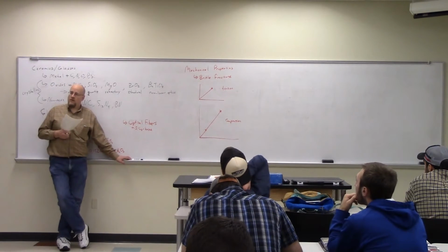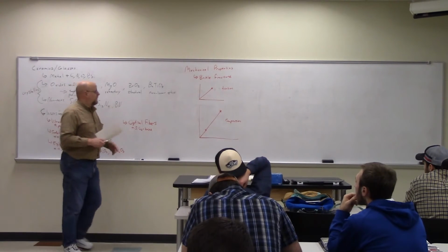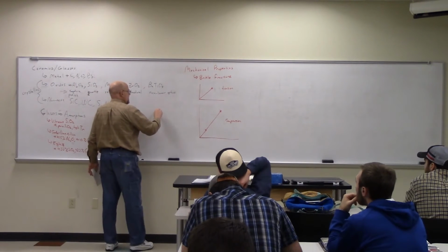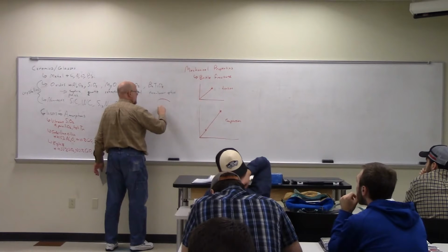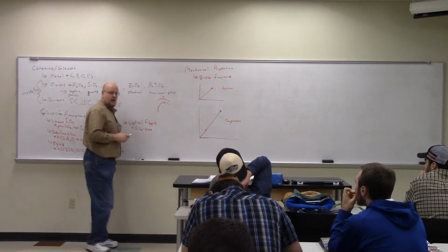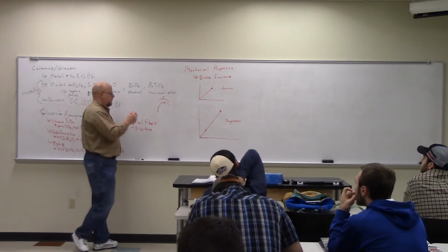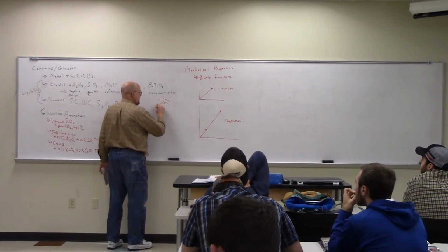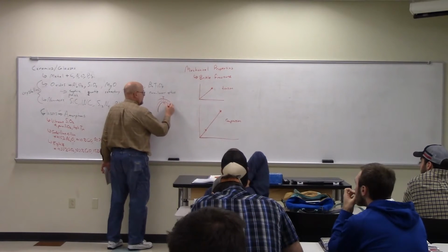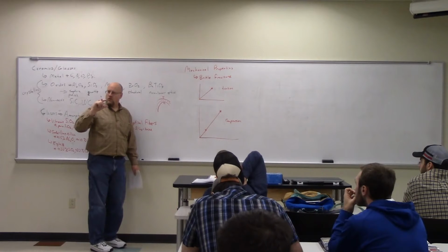If you do the mechanical analysis, the thinner it is, the less stress you get on the outer edge. If I take a beam that's this thick and bend it, there's a big tension on the top and a big compression on the bottom. The center line doesn't have any tension or compression, and the further you are from the center line, the more tension you have.